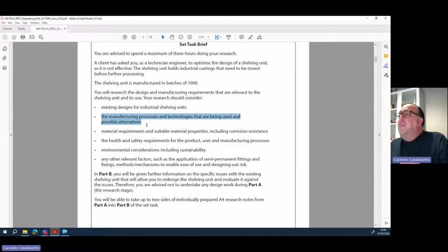So you can now have a blank, because the blank has to be folded. Okay, so how are you going to fold it? On a manual machine? Just remember there's a thousand of these to be produced, so think about automating the process here. Think about using a CNC brake press, or it could be just a manual brake press. They do the same thing, but with the manual brake press you just do one bend at a time, and it's set just for that one bend and doesn't adjust itself. Okay, I'll let you look into that sort of stuff.